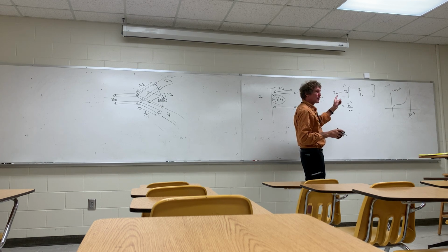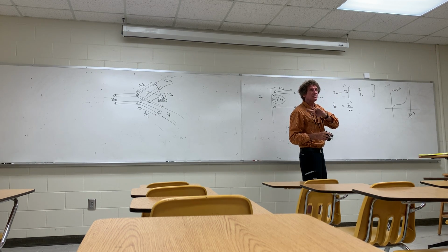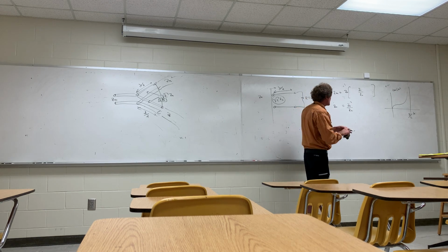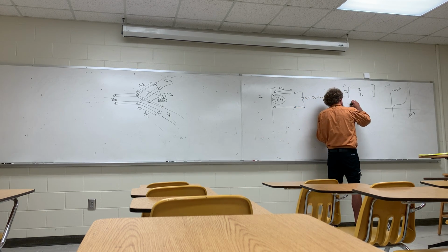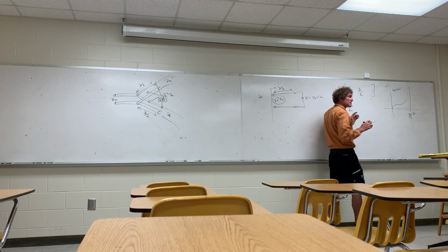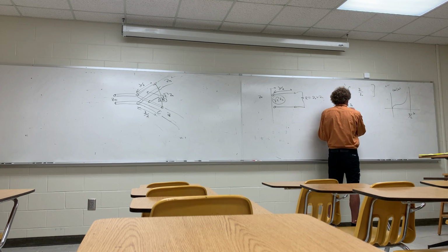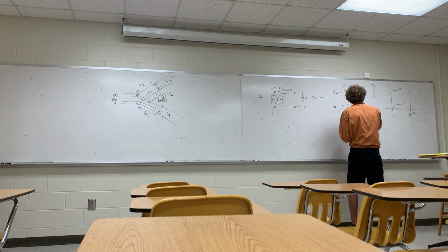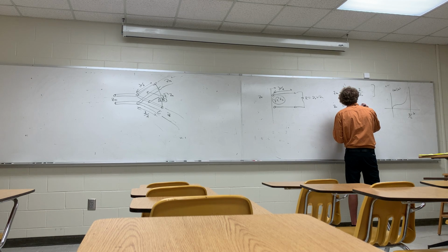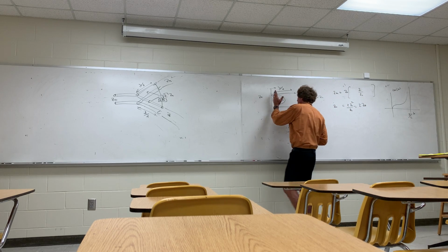Now, for our line, our Z naught is what? Square root of 2 times Z naught. Follow me? Because look here, that's what the characteristic impedance is of the Wilkinson's divider. The load is just Z naught, right? Just follow me on this. So Z naught squared on top, this is simply equal to 2 Z naught as the input impedance to this line, right?